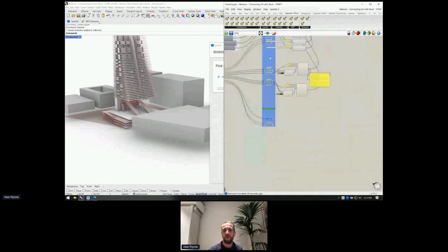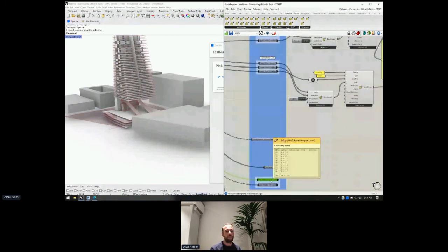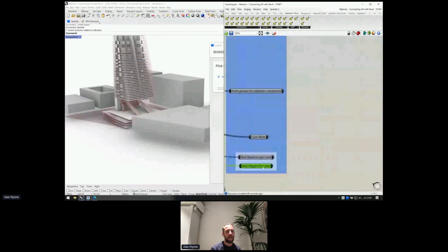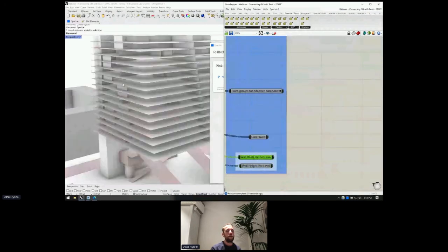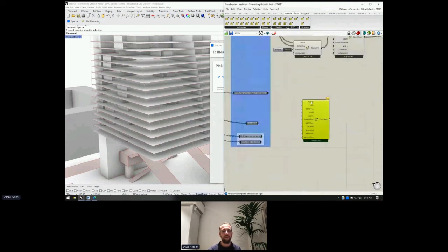And so once we've done that, we can also start taking care of the different walls and the different inner walls that we have here. So how do you create a wall in Grasshopper? Well, the same way that we created everything else. We just double click and write Revit wall. And then you will see that you have several different options here. You can create a wall using a curve and a height. You can create a wall using a face, create a wall using a profile, or create a wall using a curve and levels.